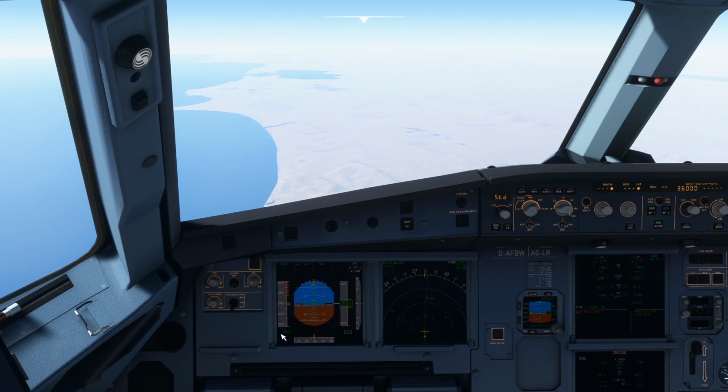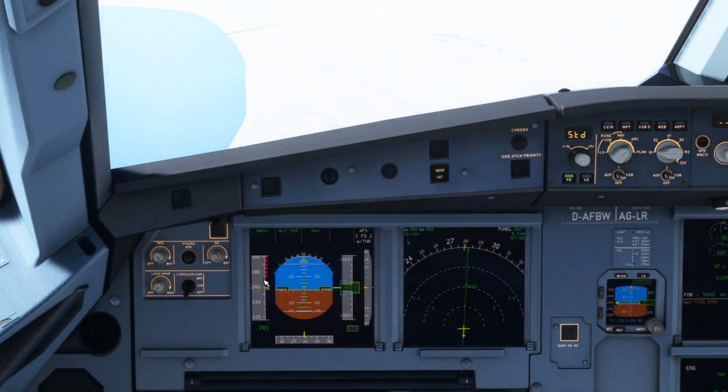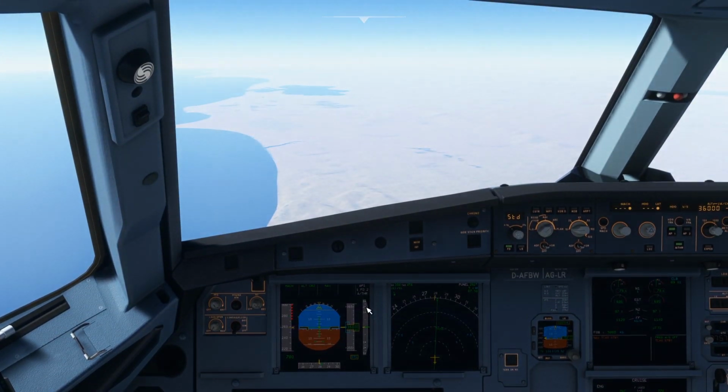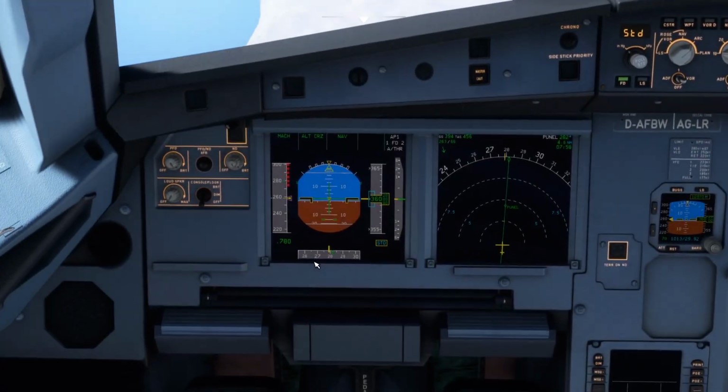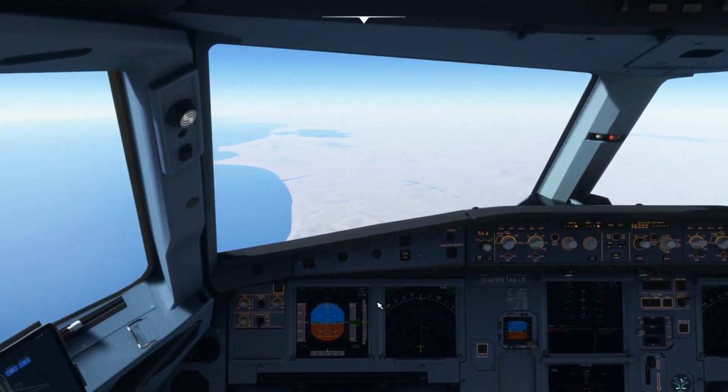Right now, if I set it to 0.8 Mach or 0.85 Mach, I think we will be overspeeding, because you can see this red mark. We don't have to go higher than this. So it's better to have it between 0.75 and 0.8. Right now, how much is the Mach? It is 0.78, as per the cost index. So 0.78 is the speed.